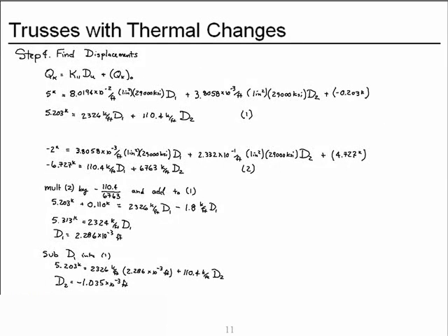We were then ready to combine the stiffness matrix coefficients with the fixed end forces in the equation shown here. And since there were only 2 unsupported or unconstrained degrees of freedom, our system of equations is only a 2 by 2, 2 equations, 2 unknowns.